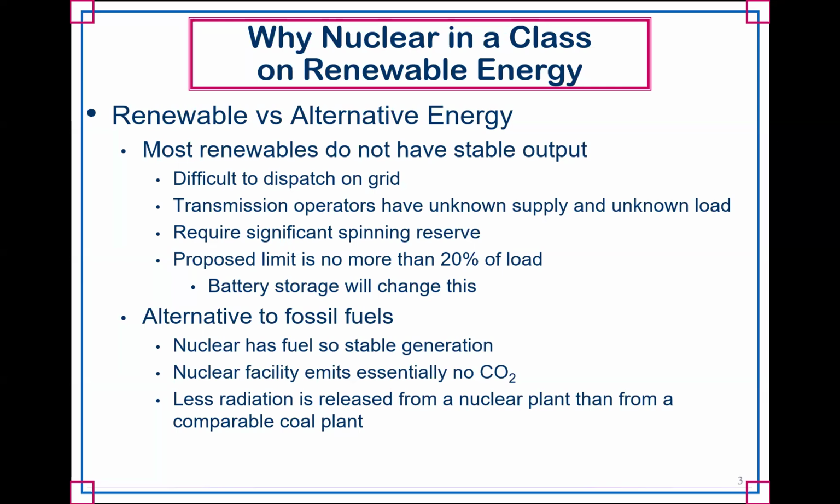Then what we'll see is that we can have the battery pick things up. And so it can support more of the load when the renewable energy sources go out. And so now, as long as you have sufficient battery storage, you can start to push more and more of these renewables to actually maximize the resource that's available. And so battery storage has huge implications for improving the amount of non-dispatchable renewable energy that can be operated.